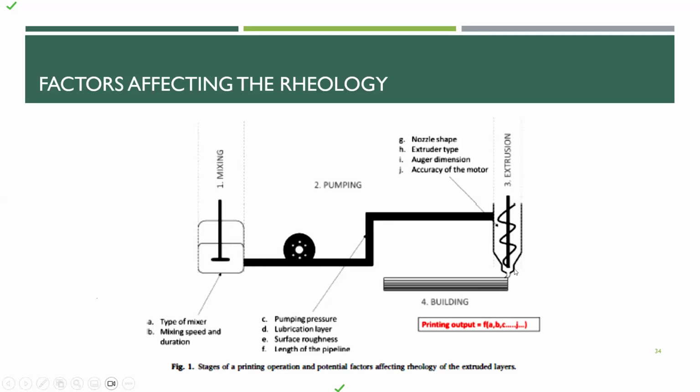But after 10 or 15 minutes, the concrete starts to harden a bit, not set, but slightly less flowable. Then you can increase the speed of extrusion to control the layers. If it is done manually, like during printing, we have to do this. For a robotic system, it's not that critical.